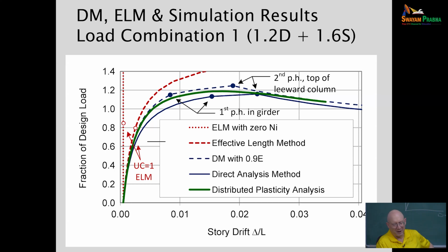But in 2005, AISC started with the direct analysis method. So if you're going to use an effective length method still, the worry, and one of the reasons to go to methods like the direct analysis method, or comparable methods in Eurocode that don't have a stiffness reduction but a larger notional load, the purpose of doing those is basically to have a better understanding of what's really happening in the structure.